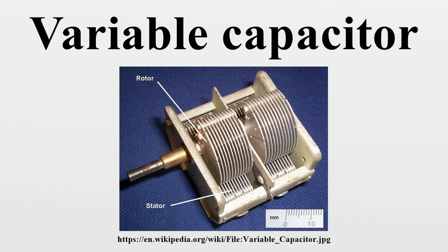Very cheap variable capacitors are constructed from layered aluminium and plastic foils that are variably pressed together using a screw. These so-called squeezers can't provide a stable and reproducible capacitance. However, a variant of this structure that allows for linear movement of one set of plates to change the plate overlap area is also used and might be called a slider. This has practical advantages for makeshift or home construction and may be found in resonant loop antennas or crystal radios.